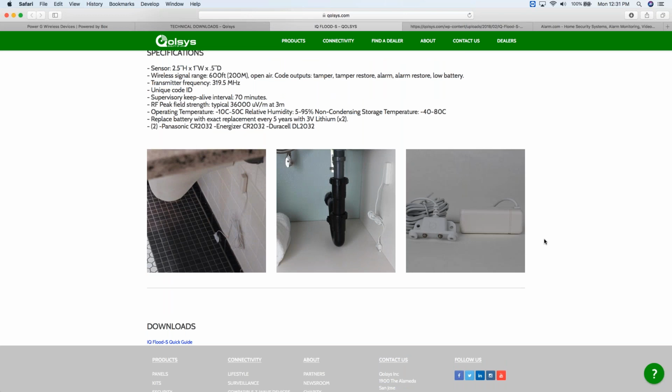Now, this contact does take 12 seconds to trip. We get this call all the time. A technician will install the flood sensor and put it in a bowl of water, or use a screwdriver to short those two contacts, and it never trips. But there is a threshold.